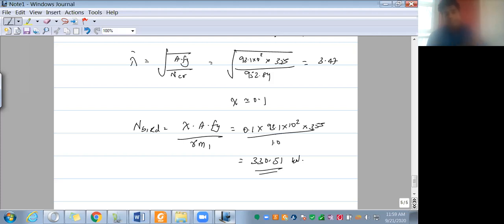The global buckling is done in a similar way that we did. So that is NbRd. So you have to determine this factor chi, the reduction factor, and that reduction factor chi can tell us whether this will buckle before actual failure or actual failure will occur. Okay, so those things we can see from these two calculations.